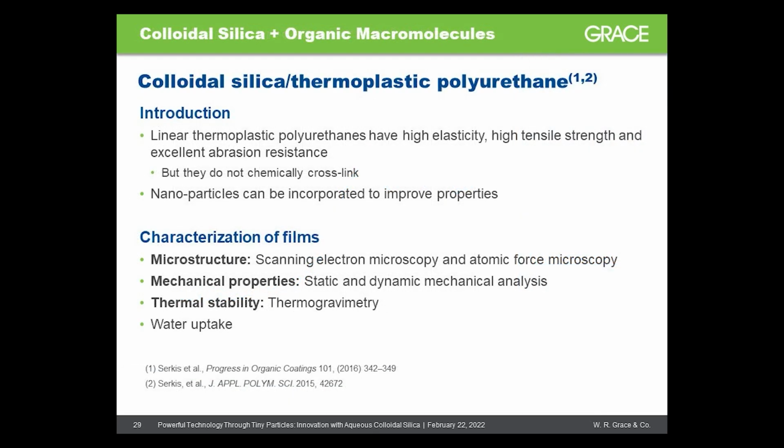The first application we will highlight involves incorporation of colloidal silica into a linear thermoplastic polyurethane system. These polymers typically have high elasticity, high tensile strength, and excellent abrasion resistance. We chose this system because it was a relatively recent study wherein the mixtures were both very well characterized and demonstrated strong improvement in selected functional properties for the mixed system.